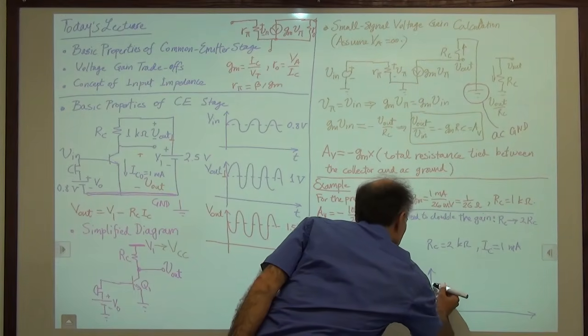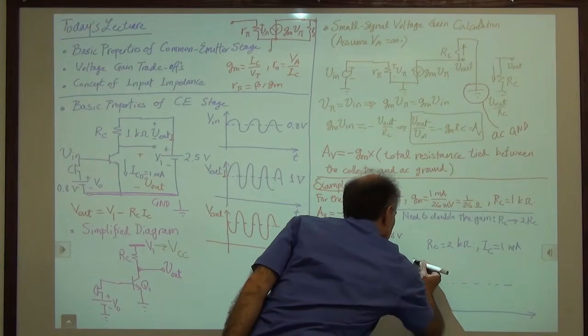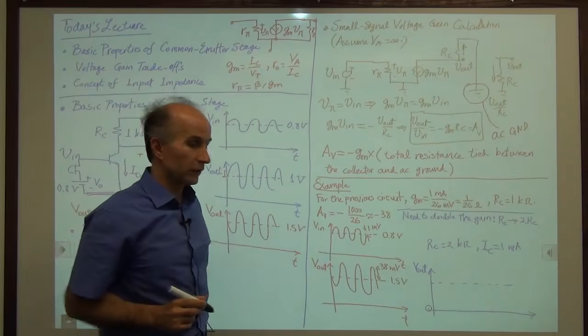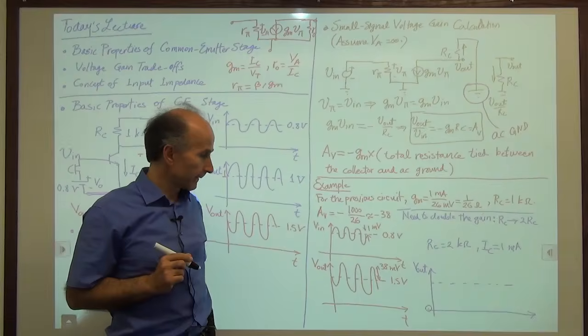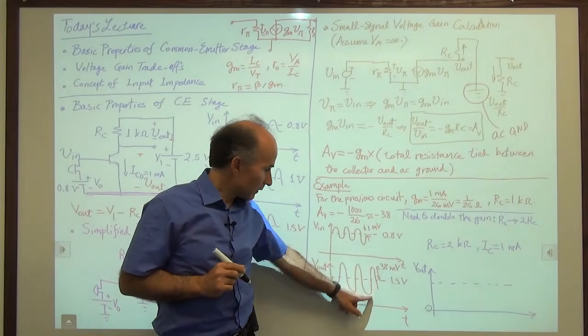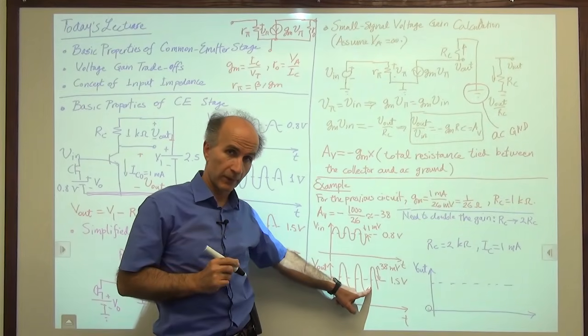The microphone and the bias voltage for the base emitter are still the same. All we did was change the collector resistor from 1 kilo ohm to 2 kilo ohms. All right. So what we are hoping is that this signal swing now is 76 millivolts instead of 38 millivolts.